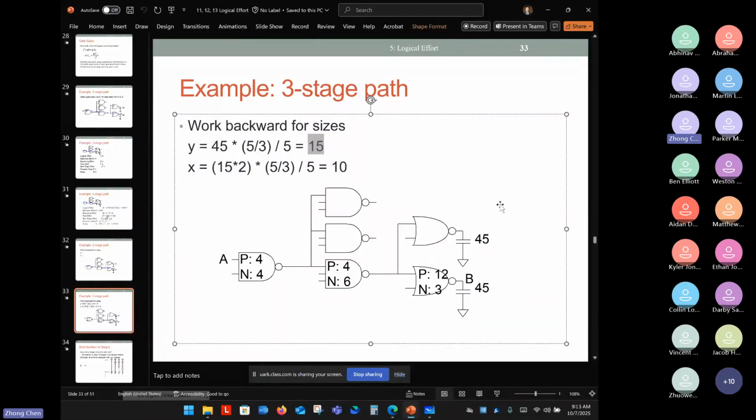So in your mind, you should be able to draw a schematic: two PMOS in series, two NMOS in parallel, and the size will be 4, 4, 1, 1, so that the P network effective resistance equals the N network resistance R. No matter which NMOS turns on, the effective resistance equals R as well. So you get 4411, and the PMOS and NMOS ratio is 4:1. If you have the PMOS NMOS ratio for this particular gate, and you know one input's total capacitance, which is the PMOS capacitance plus the NMOS capacitance, equal to 15, then you should be able to determine the P and N sizes, which are 12 and 3.